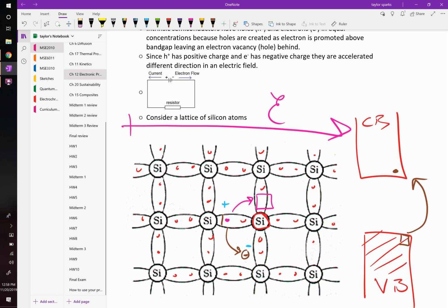If I jump out of an airplane, the coefficient of friction of my body against the air, we could quantify that. And the analogy for electronics is what we call the mobility. It's essentially like the drag force that it feels in response to an accelerating force, right? The electric field which causes it to accelerate. It experiences a drag. And what's interesting is that this free electron moves, but it experiences a different drag than the hole. Is that weird? It's a little weird. It's the truth, okay?